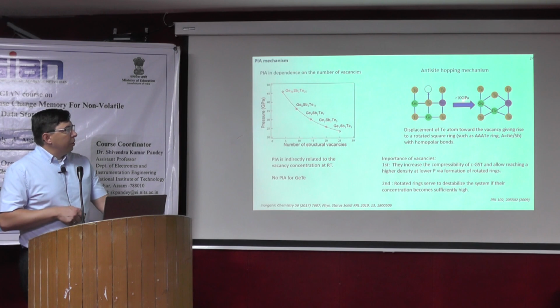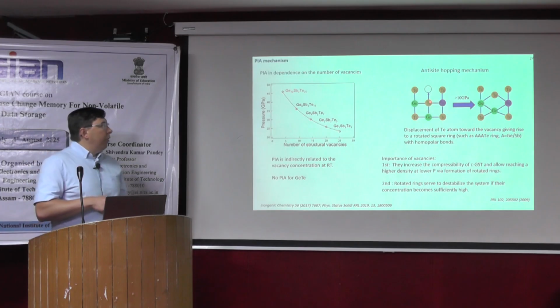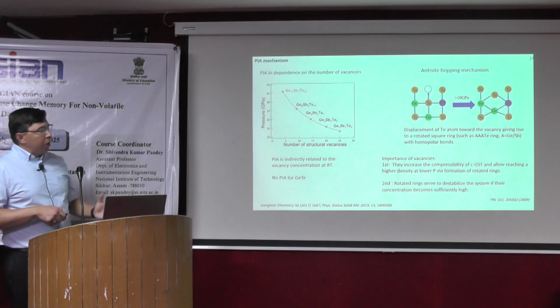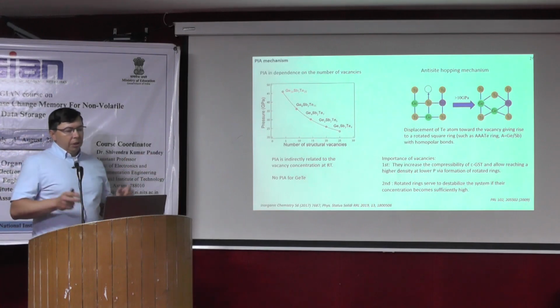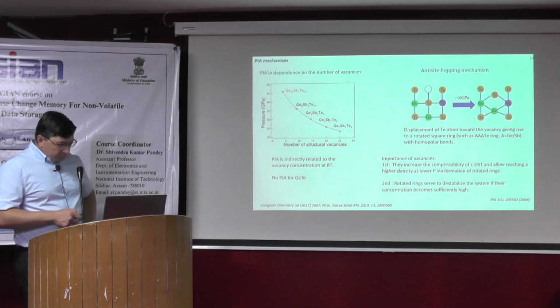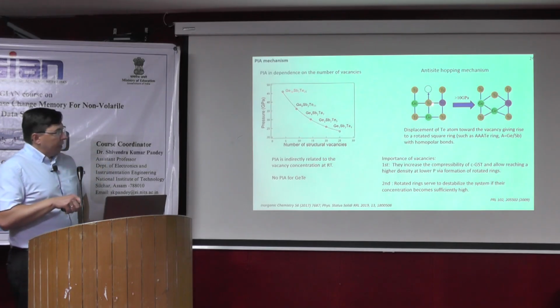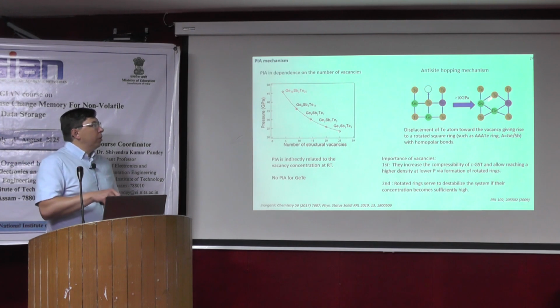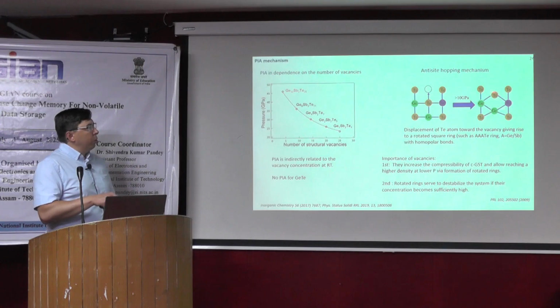If we consider our structure, the cubic structure here consists of germanium, tellurium, germanium, tellurium, this is the cubic FCC. And then we have a vacancy here. What happens during compression, we know already that the system can get a little bit denser. And here tellurium shifts to the vacancy, like here, and then we have a new structure, having tellurium, germanium, tellurium.